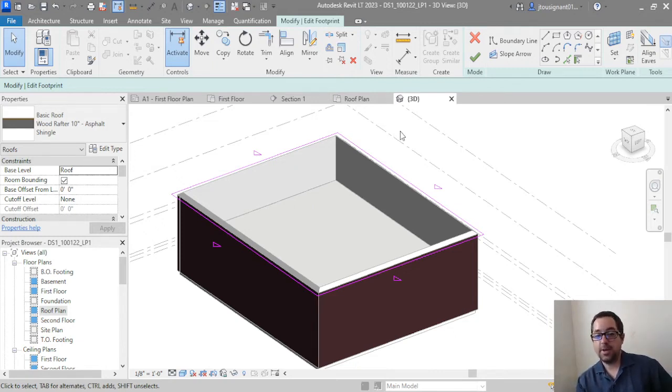Now when I double click on families, it goes into the edit type properties. So not only is it not a hindrance that hangs me up by having to go into the edit family and then close it and say don't save, it can actually be a tool to save me a couple seconds if I get used to it. I haven't opened the edit properties that way yet.